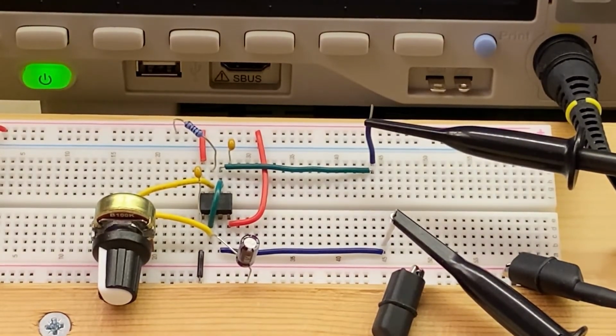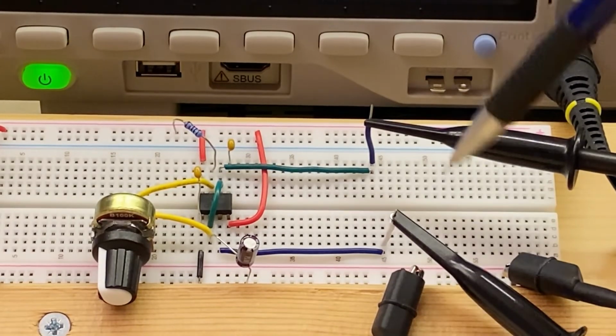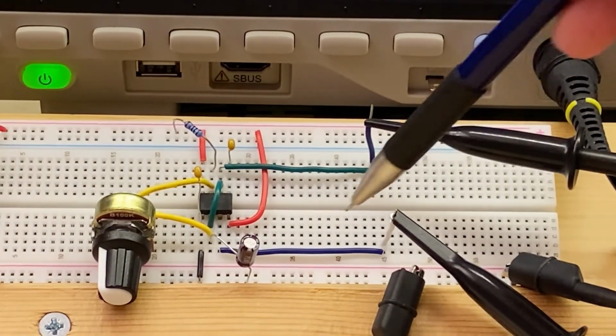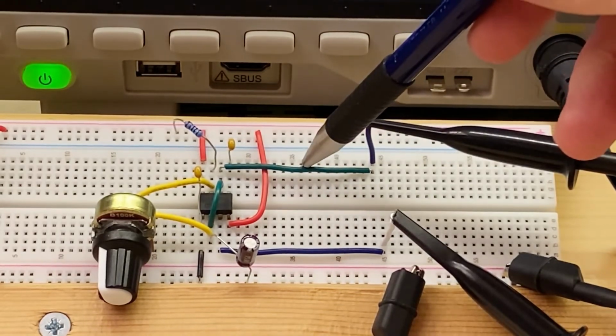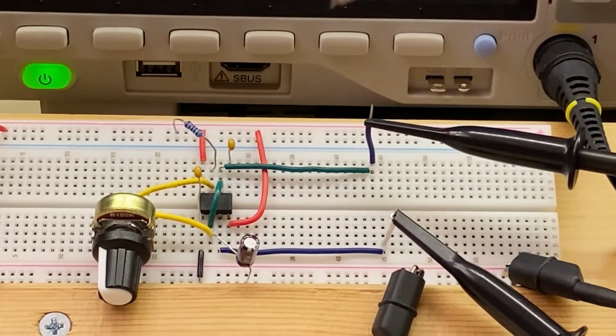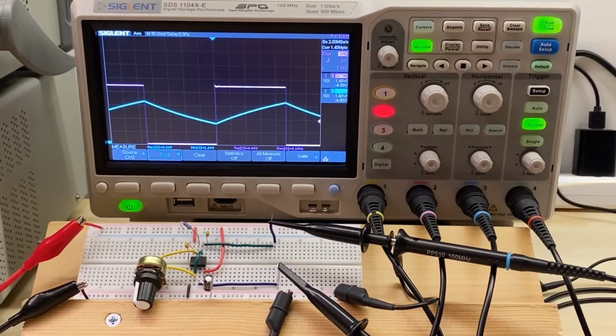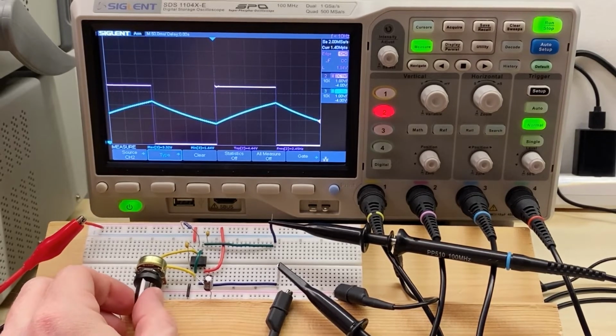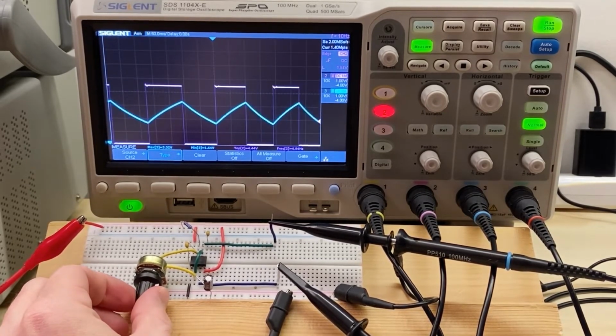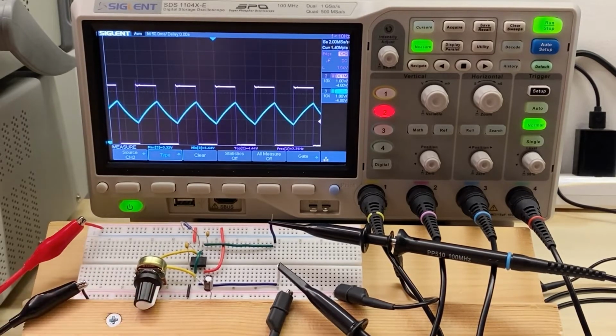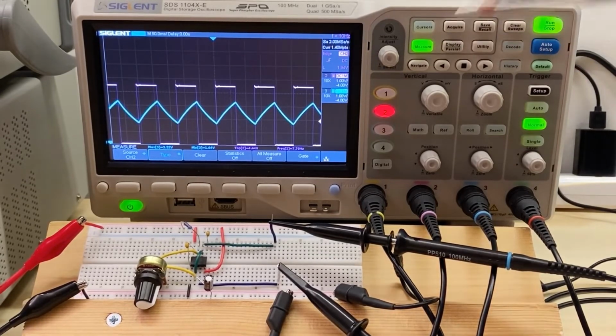And also as you can see, I have oscilloscope probes attached as well to the output and also to the voltage across the capacitor. So we can see the capacitor charge and discharge. Okay, so we see our square wave, and maybe if I increase the frequency, it'll look a little better. So the purple trace is the square wave, of course, and the other one is the voltage on the capacitor, and it looks just like the diagrams, or the plots I should say, in the data sheet.